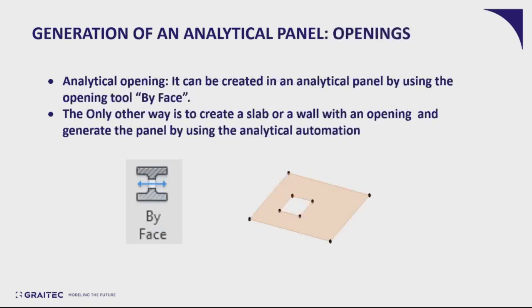And by creating an analytical panel, there is still the option of having an analytical opening, which means that when you transfer this model to Advanced Design, the opening will be identified by Advanced Design, and the finite elements analysis will be performed considering this opening.